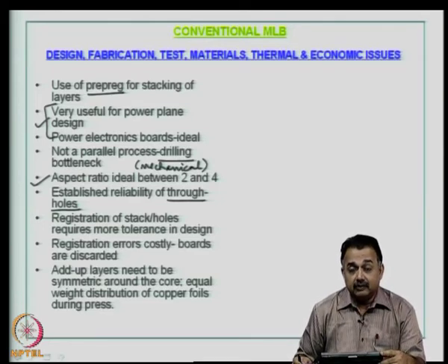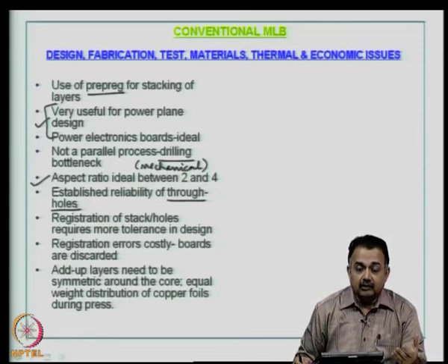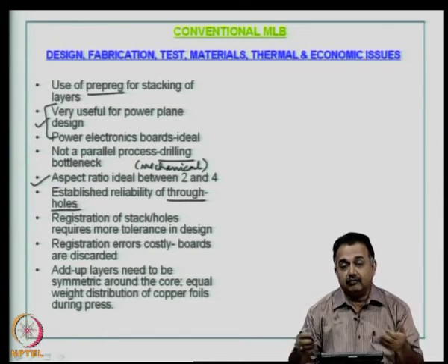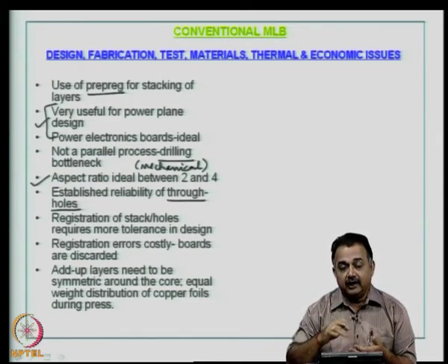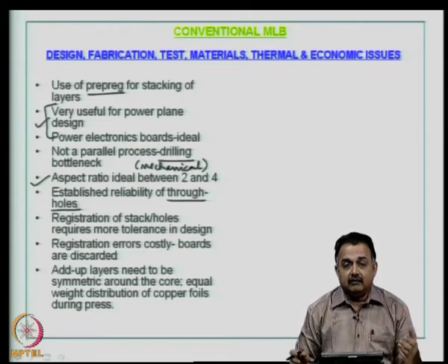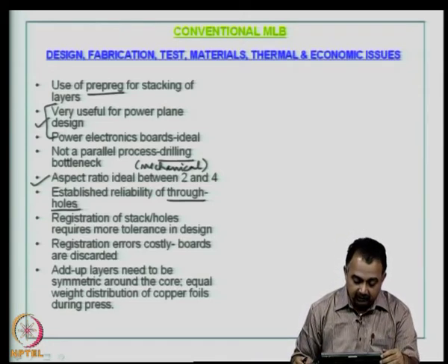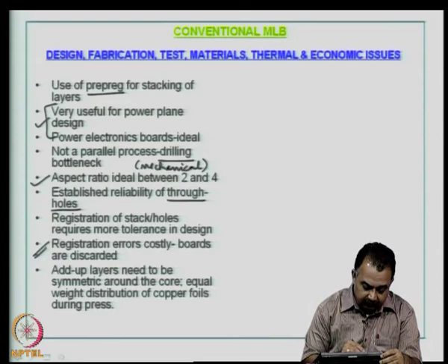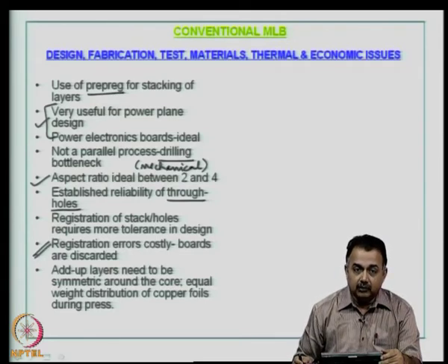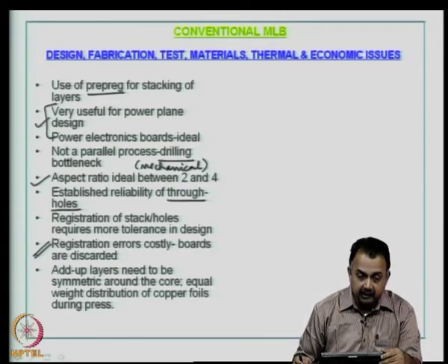Registration errors will be more costly. In some cases boards are discarded. So, make sure as a designer you understand in a multilayer board design what kind of tolerances you have given, especially if you are drilling, for example, layer 1 to 8, and if you finally see one of the inner layers is not connected at all. So, this to me is very important both from the design point of view and manufacturing point of view.